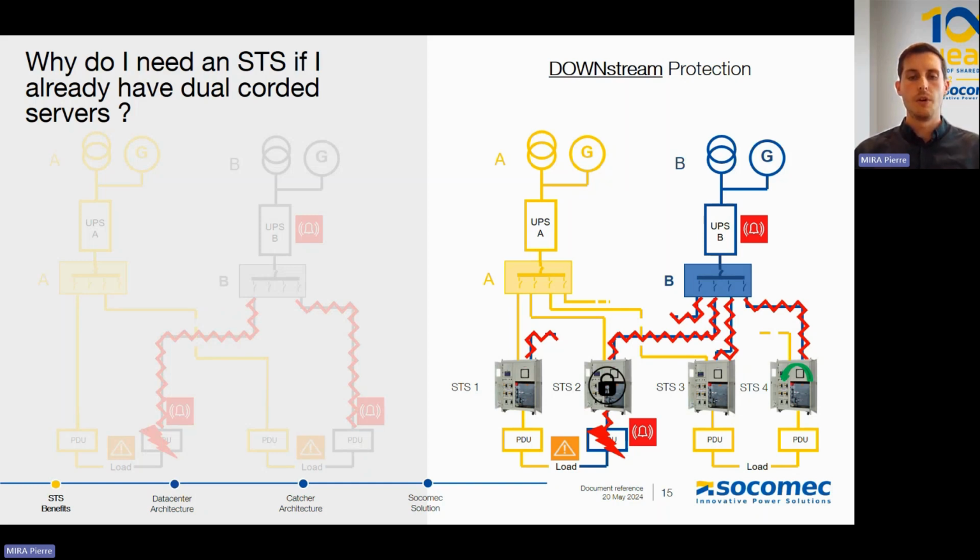We can call this advantage load segregation, load islanding, PDU islanding. That's showing that having a static transfer switch in our installation helps us to secure our PDUs, indeed securing our loads.